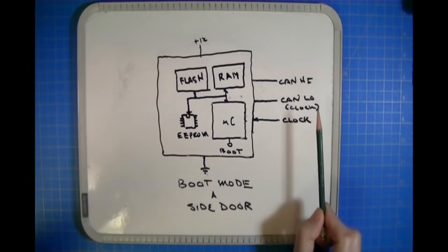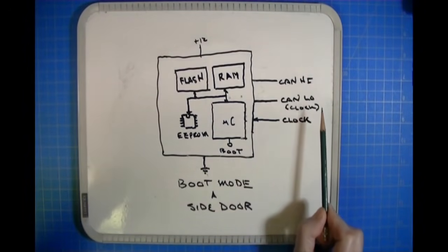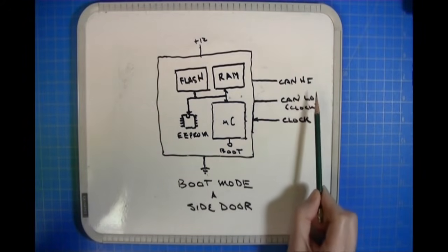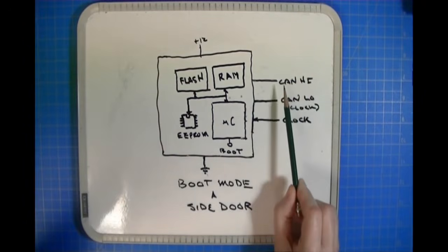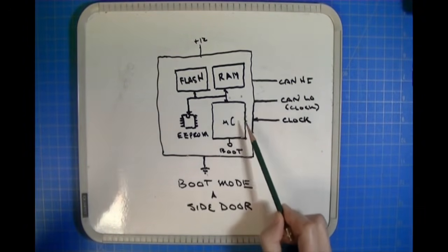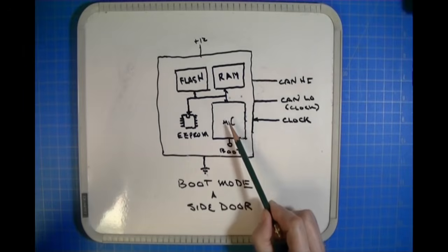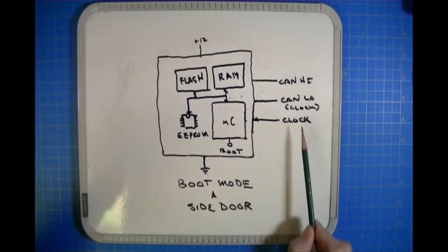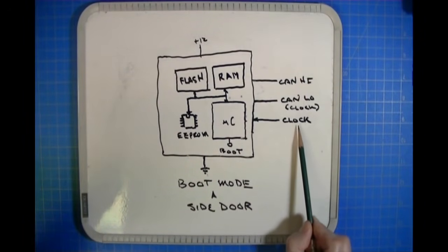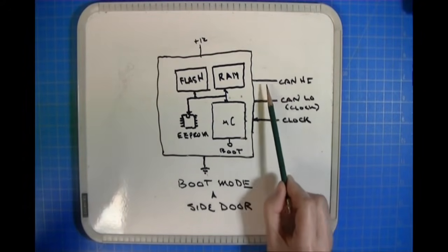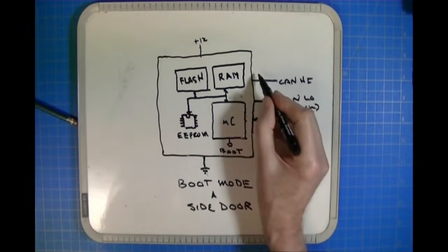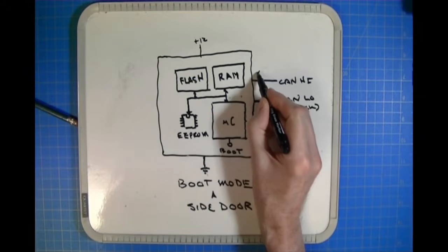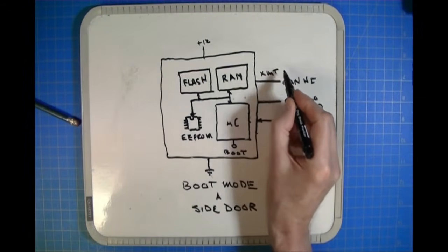And the way that it works is you have to have synchronization, because the bits that are now flowing over these lines have to be synchronized with the receiving circuitry that's in the microcontroller. What I've shown here is a signal called clock, and the clock signal basically synchronizes the bits as they come in. In this case, maybe I should mark this. Let's say this is transmit and receive.